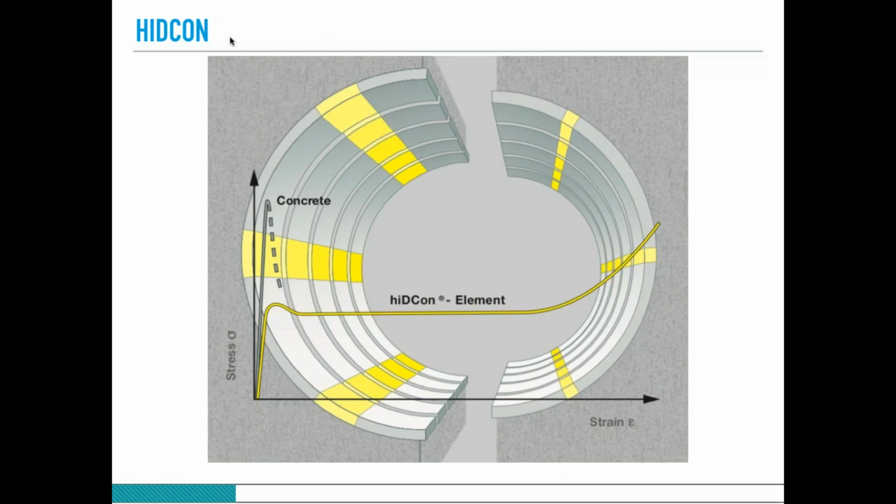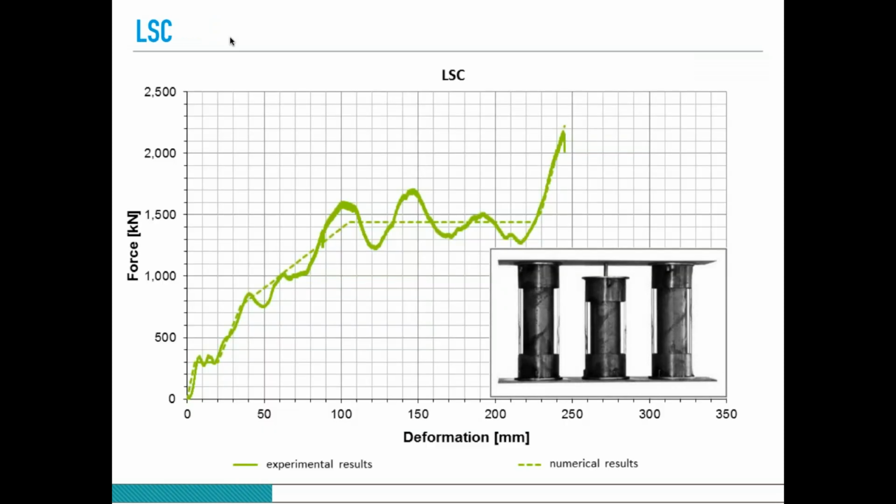It is not yet a mass product, but they can be used in mechanized tunnels as well, and the efficiency of the lining will increase significantly. LSC yielding elements, or lining stress controllers, consist of a group of yielding steel tubes fixed at the top and bottom by means of two rigid plates. The outward movement of these tubes can also be controlled by the outer tubes, as shown here.